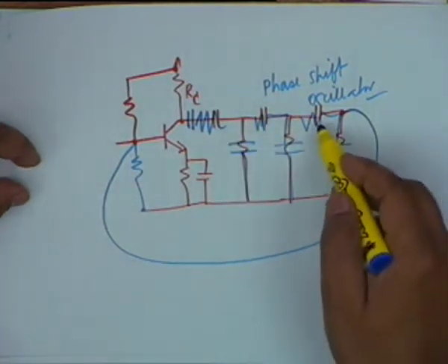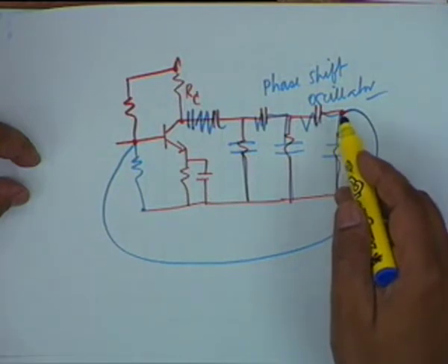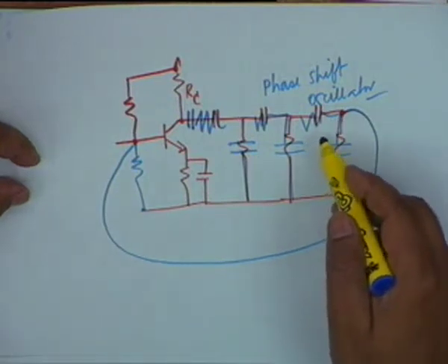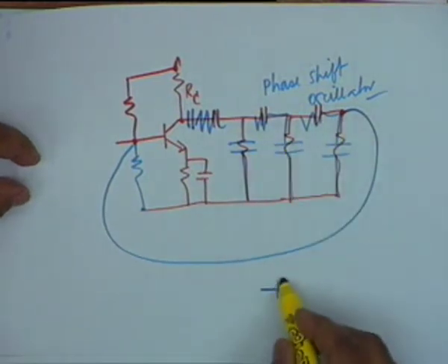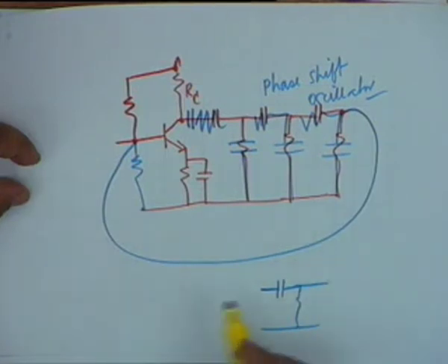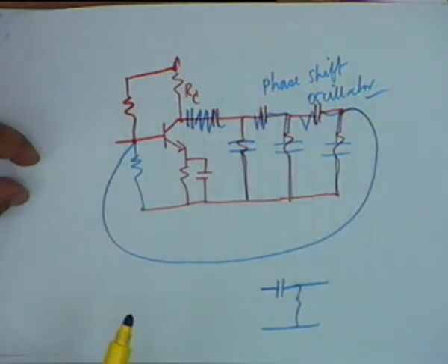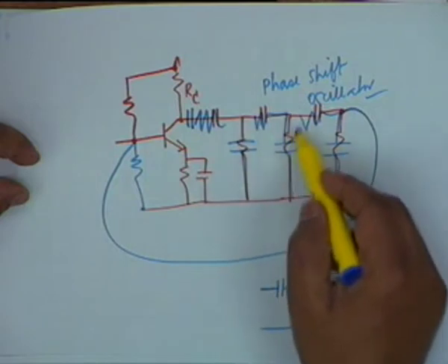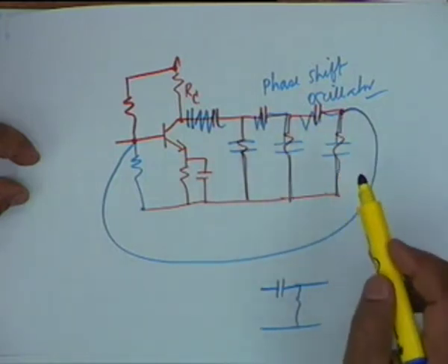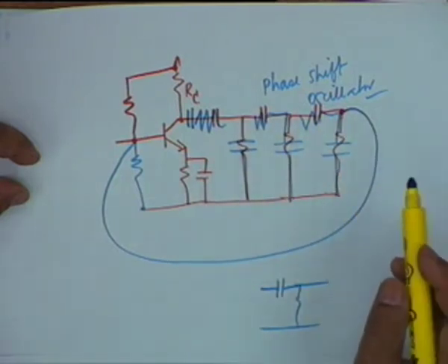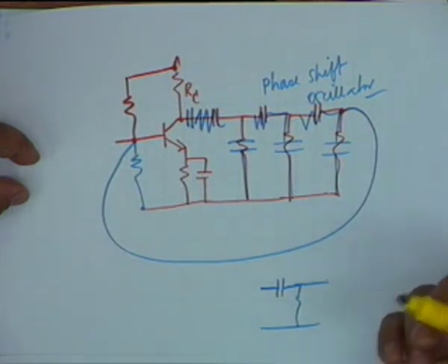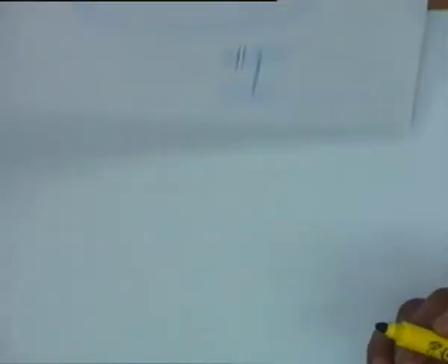This would be a lead circuit, pi 180 degrees leading, isn't that right? Because in the CR circuit, the output is leading the input. On the other hand, if it is an RC circuit, the output shall lag the input, and therefore, if we take RC, RC, RC, it shall be minus pi. Agreed. Plus pi or minus pi, it does not matter, either way it shall work. But the problem is how to analyze this circuit.